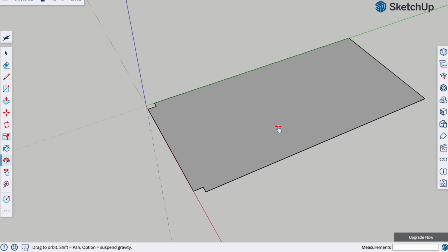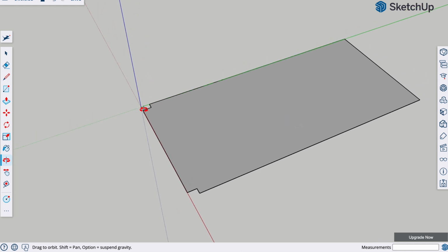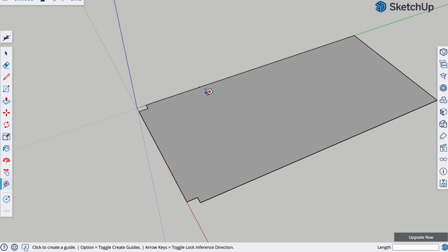Next up, there are often wheel wells. In your diagram, it's going to tell you where the wheel wells sit. Say ours are 3 feet from the back of the van. So we're going to get that tape measure and measure 36 inches. It's going to drop a guide point. And from there, your diagram is going to tell you how wide those are. Let's say they are 12 inches by 4 inches. Drop that. Actually, that doesn't look big enough. 15 inches by 5 inches.